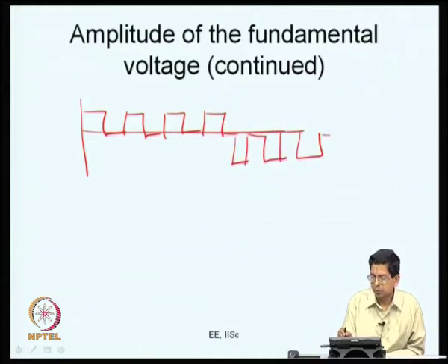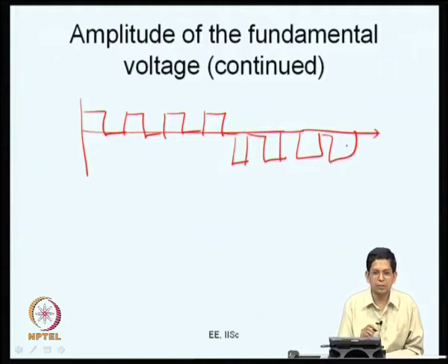This is an example which is very similar to the previous examples that we saw. You introduce some notches, few notches, or more notches, and more notches means the device inside the inverter switches more number of times. So that places an upper limit. In the olden days, the device was switched at very low frequencies. So in a 50 hertz cycle, one could have very few notches. Nowadays, modern power electronic devices can switch at much higher frequency, particularly if the power levels are not too high, not like tens of megawatts. You can certainly do that now.